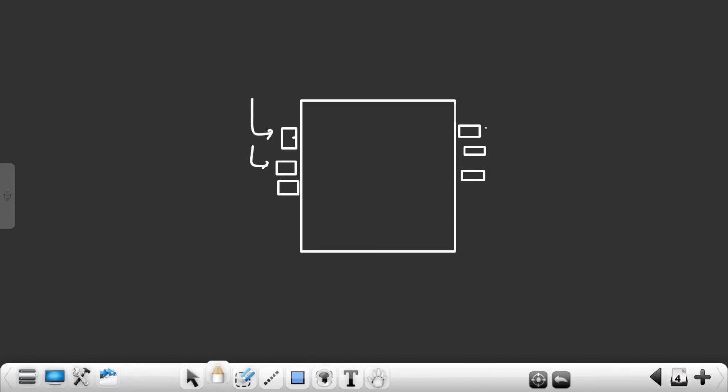So these bits you will get from the output ports. You will verify with the previously recorded values in software, and compare with that. If both are correct, then what you do? You tell that this IC is working fine. If both are not correct, you will throw this IC. It's not working fine.